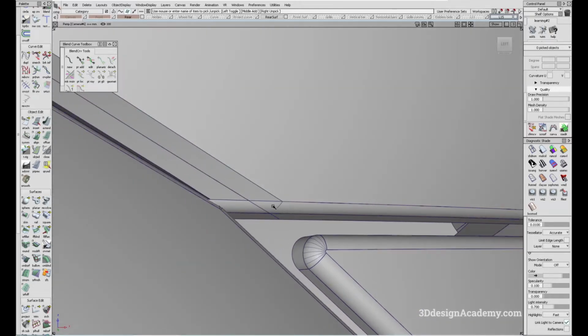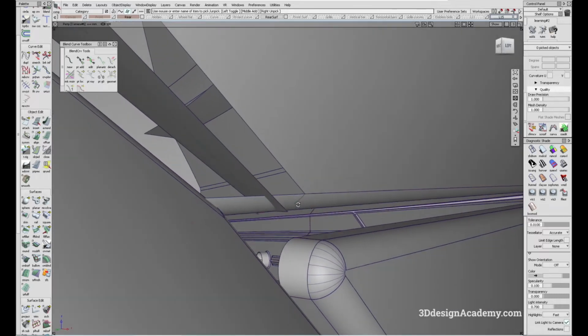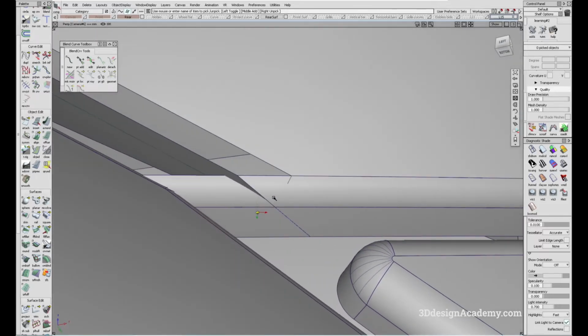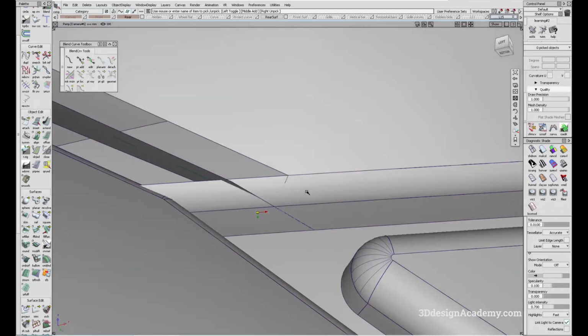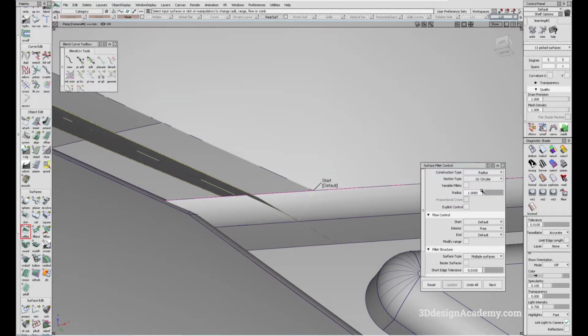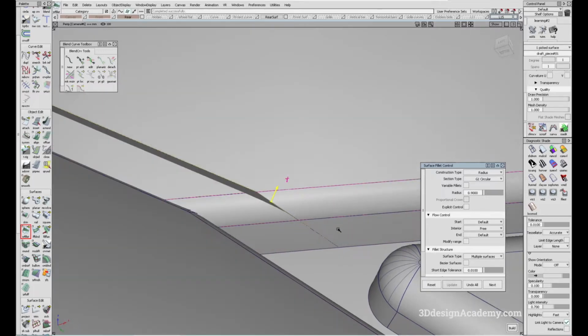And if I were to do the fillet over here and make this separately as a 1.1, then I don't think this is going to run through very well. So in this case, I'll just say 0.9 and just call it done. Okay, so I'm just setting this as a 0.9.